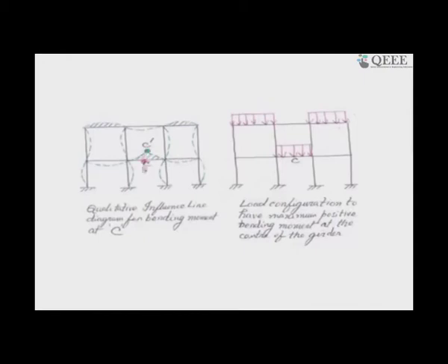If the internal hinge is formed, then I can say that this portion should go up, but since this is a statically indeterminate structure, this joint, which is a stiff beam-column junction, will not give way, and it will try to maintain the 90 degrees with respect to the columns and the beams. So, because I have lifted this position, this is the bent portion of the girder.